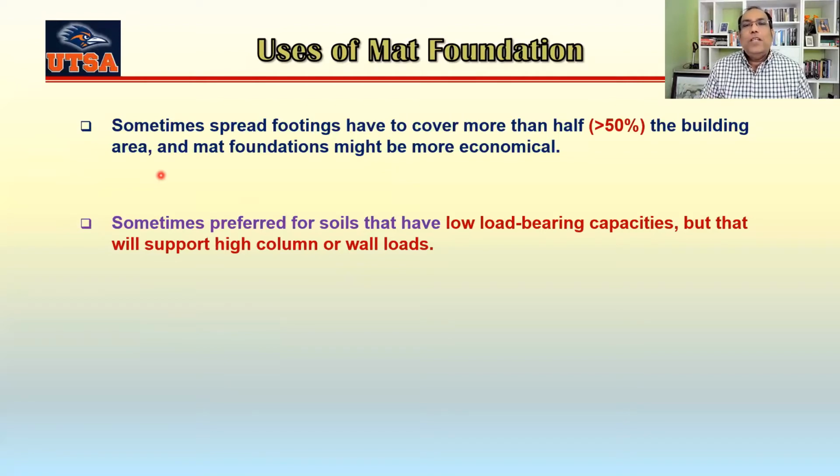In that situation, we use mat foundation because it can be compensated by the amount of soil we dig out from there. We'll talk about compensated foundation later in this lecture. But for now, just remember that if the soil has low bearing capacity but the load coming from the building is high, then definitely we can consider a mat or raft foundation.